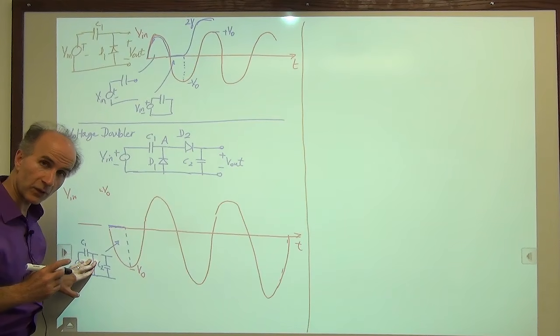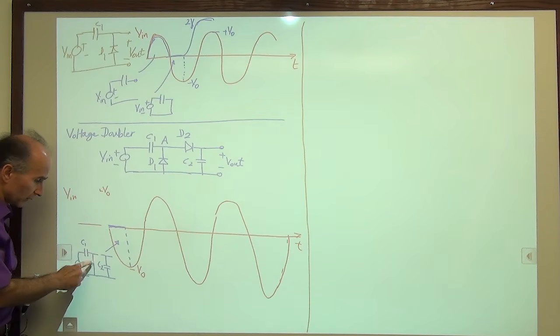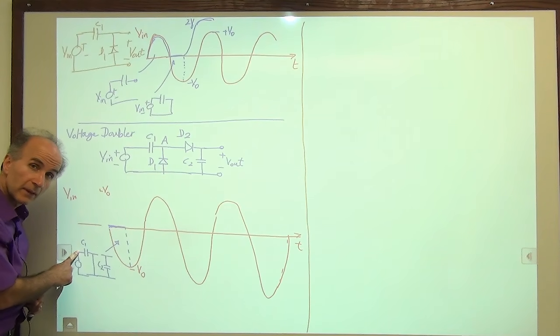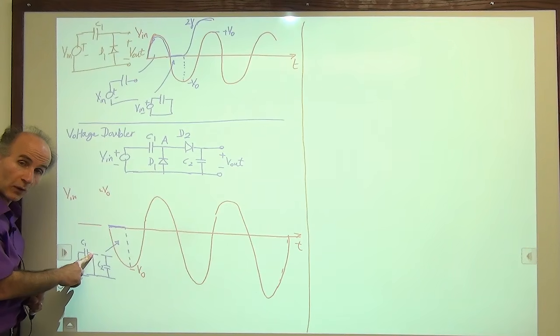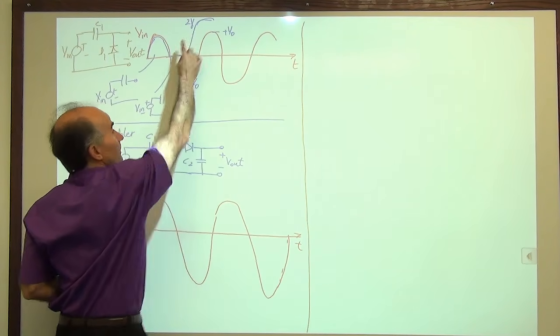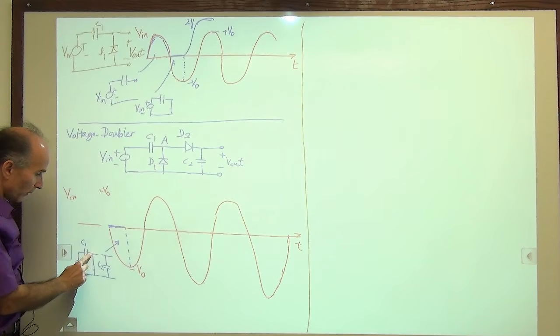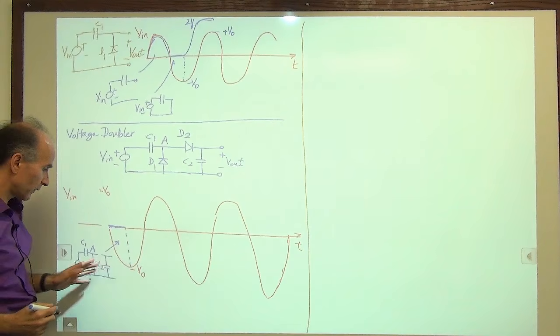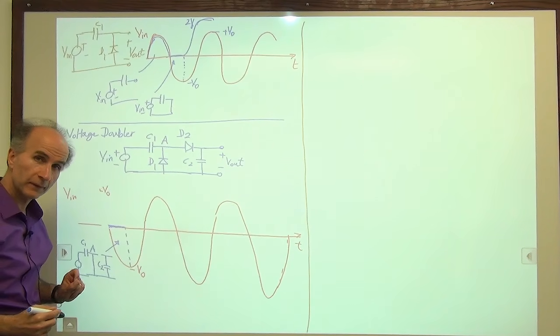So now here's the situation. We have 0 volt here. This diode is turning off, and this voltage is going up. So what happens at this point? This point also wants to go up. Remember, the output wants to go up. So this point, point A, wants to go up. So let's draw what the circuit looks like past this point.